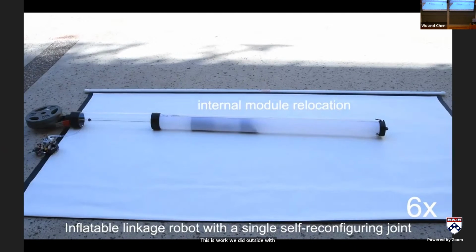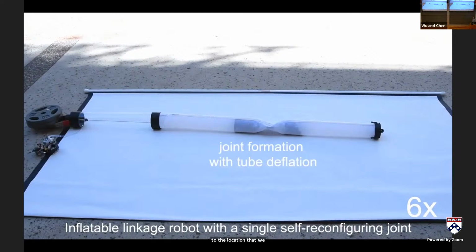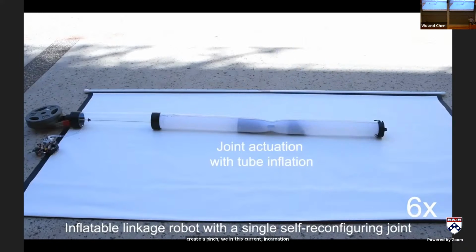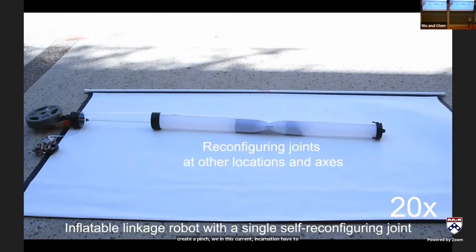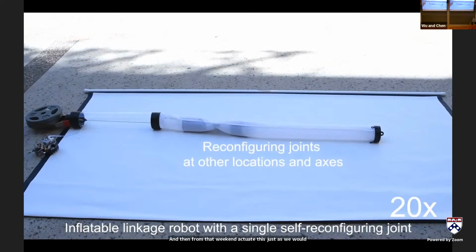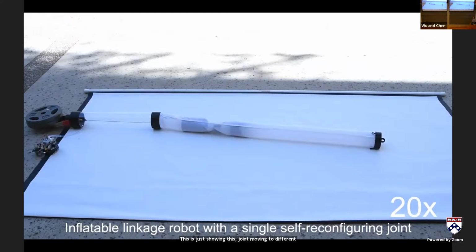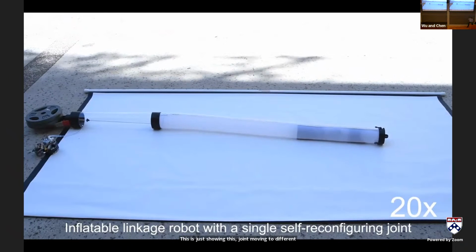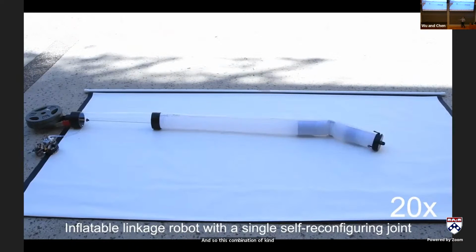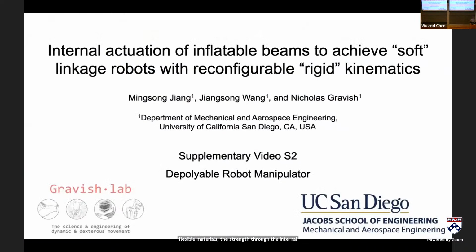And so we inflate the tube, we move the link to the location, or the joint, excuse me, joint to the location that we want to form a joint. We create a pinch. We, in this current incarnation, have to depressurize a little bit to create the pinch. And then from that, we can actuate this just as we would actuate a simple 2-link system. And so this is just showing this joint moving to different locations. And so this combination of kind of flexibility from the flexible materials, the strength through the internal pressurization and the reconfigurability allow for a lot of interesting kind of adaptive type behaviors in these systems.